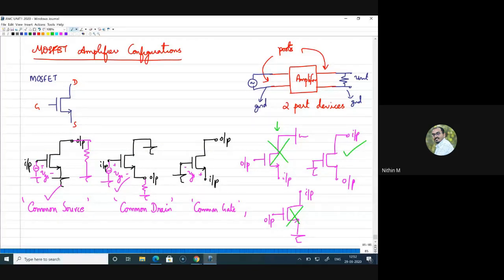Yes, Namit, VGS is 0. We are not actually giving any VGS in this case, so we cannot expect that the MOSFET will respond to that. So this is also not a valid combination for several reasons, as we are not giving a VGS, and some more that we will see very shortly. Now from all these 6 cases we can consider 3 as valid, 1, 2 and 3, and we have named the configurations as common source, common drain and common gate.